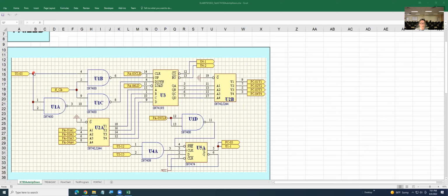Also, pin number 1 here at logic 1, you go to the NAND. They will be 0, a 0 in pin number 10 here, and the output will be 1. That's why when they count up, the clock goes to pin 5. However, pin number 4 has to be 1.